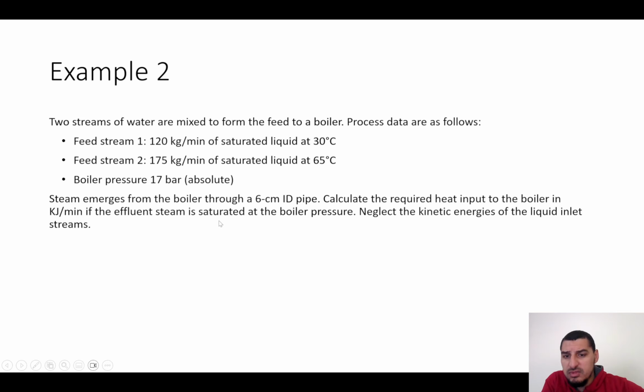Given that the effluent stream is saturated steam at the boiling pressure, we will not neglect the kinetic energy. It's not the changing kinetic energy. This needs to be clear. We neglect the kinetic energy of the liquid inlet streams. So this is the information that we know, what we have.